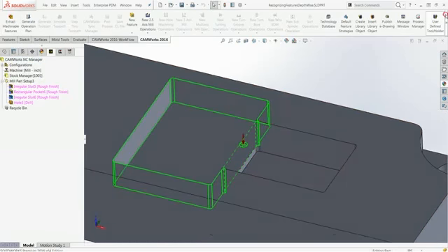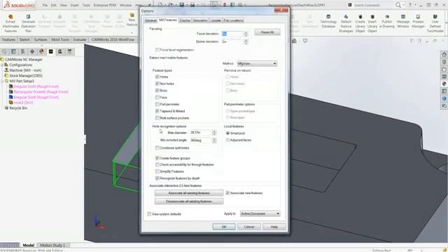So that's a nice option for selecting different features. So again, it's Recognize Features by Depth. And you can go back and forth just by checking and unchecking that box, however you want to machine it. This is available only in the manufacturing view method, so if you change to AFR, it isn't there. So it has to be manufacturing view and recognize features by depth.